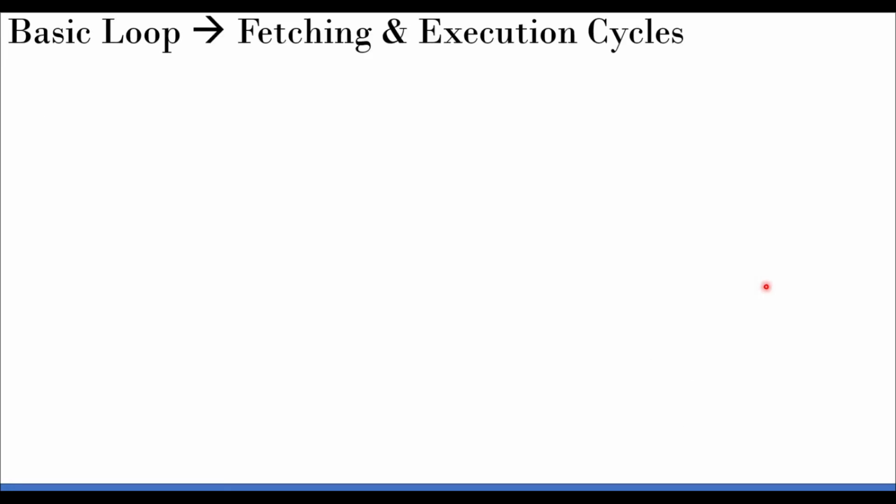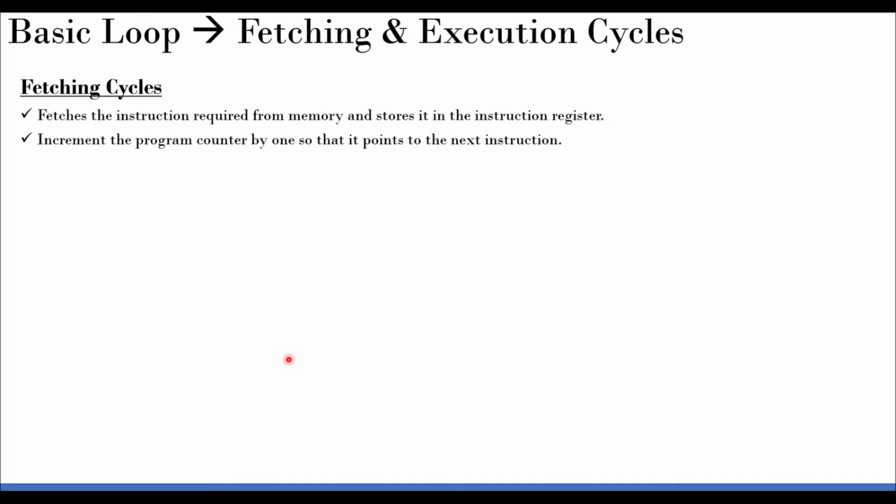And then of course, as far as the operation is concerned, there are two important aspects that you want to consider here. One is definitely the operation part, which as I said, you will concentrate on in this design. And then of course these two terms, well known to you by now, essentially form the control unit design for you, right? Fetching part, of course you know that there are two aspects to the fetching part. One is fetch the instruction from the memory to the instruction register. That's the aim of this process. But then of course there's another one, which we already saw: increment the program counter so that it is ready and stores the address for the next instruction.